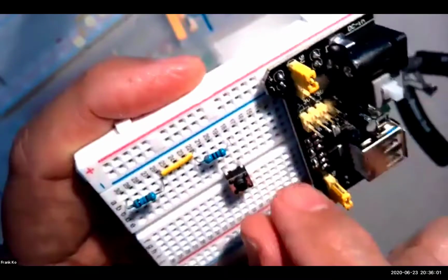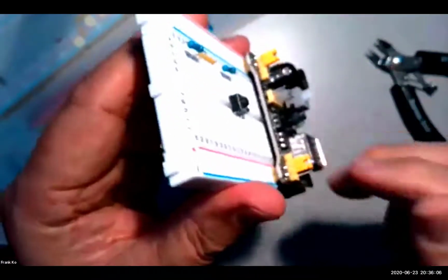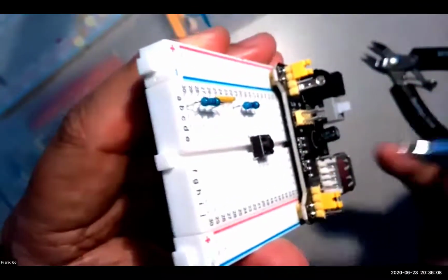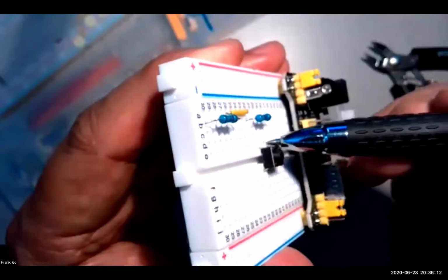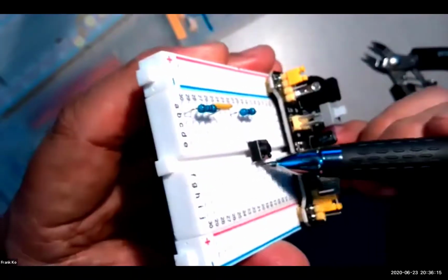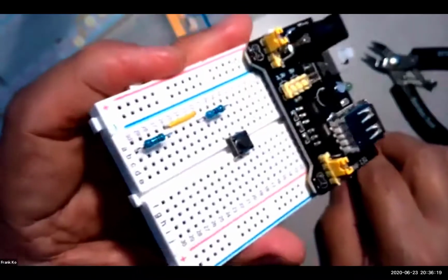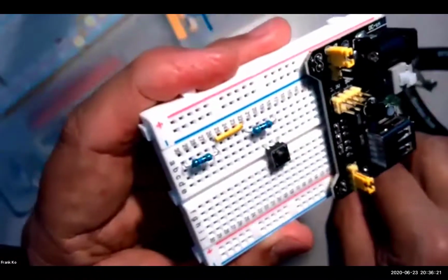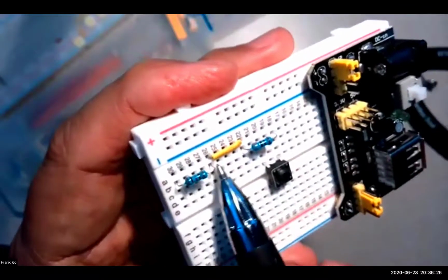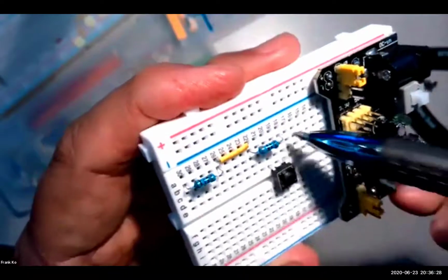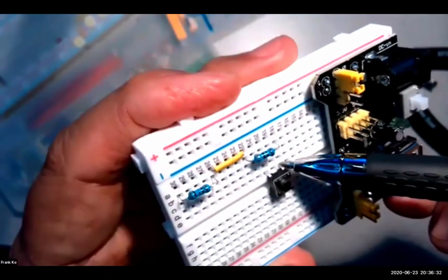If you're happy with that, now push that switch in place onto the board, and so it should sit onto the board this way. It straddles your dip support groove. So 2 sets of tines are on this side, 2 sets of tines are on this side, and you simply push it flat onto the board. Are we good with those 3 components so far? We have a resistor, 100 ohm, to a jumper, to a 330 ohm, to this upper right tine of the switch.